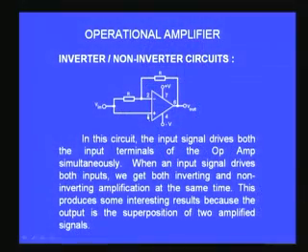You might remember we discussed the superposition theorem. I am sure many of you would immediately recognize that using the superposition theorem we can understand the working of this circuit. So what is it that we have to do? It is very simple. If you see on the screen, I now assume the V in is driving both the inverting as well as the non-inverting input. So if I now ground this non-inverting input